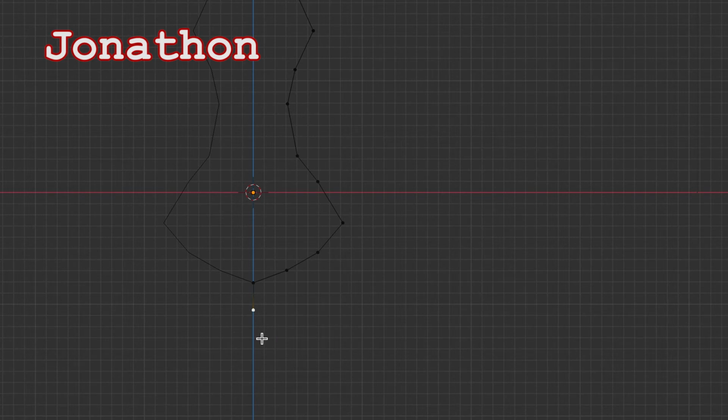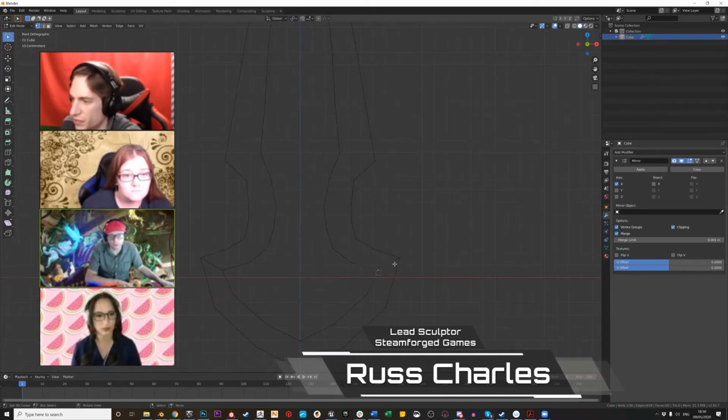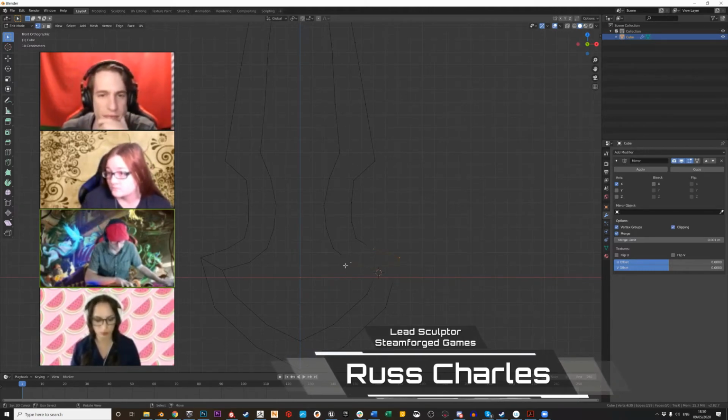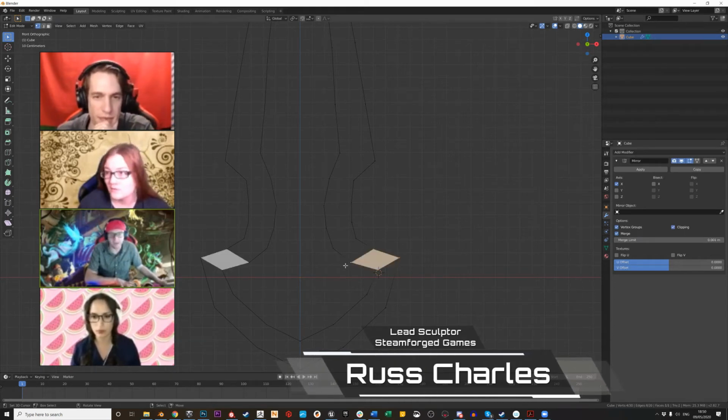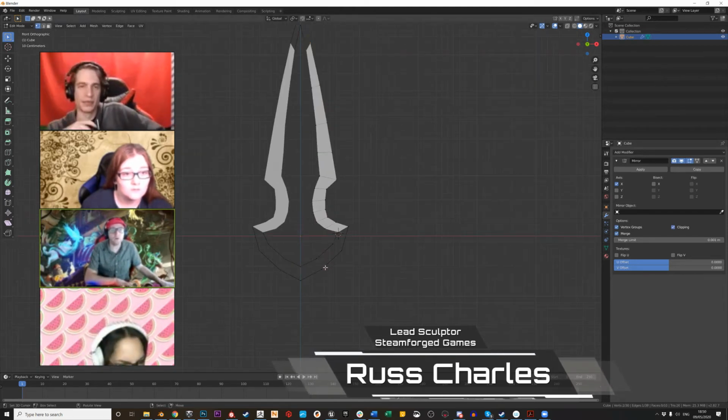What we're going to do now is basically connect all of this together and turn it into a solid. So I'll run through it on my screen. I'll do a couple and then give you guys a chance. I'm going to start from where I've got my connecting line. I could start it from down here, it doesn't really matter. All I'm doing is selecting four vertices that would form a quadratic shape, and hitting F and it will form that quad. Once I've formed one, you can select two off its edge, and then every time you press F, it will fill it in.